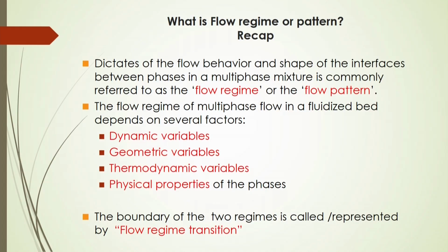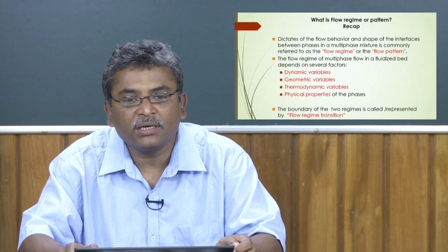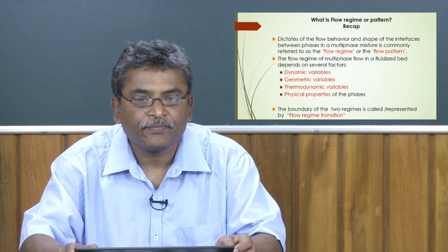If you change the density, of course, the behavior will change. With a highly viscous fluid, it is very difficult to flow or to get different flow regimes inside the bed. Even if you change the particle diameter, that is coarser diameter, you will not get the specific flow regimes for a particular operation. Then accordingly the flow regime will change and the application will be different. And also pressure effect: if it is operated at high pressure, the minimum fluidization velocity will be more in that case.